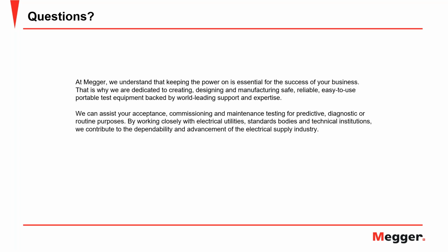So like Dinesh just said, whenever you're ensuring that the circuit breaker is going to have the ability to trip whenever it's under that ground fault condition, the only way you're going to do this is through a primary injection test.